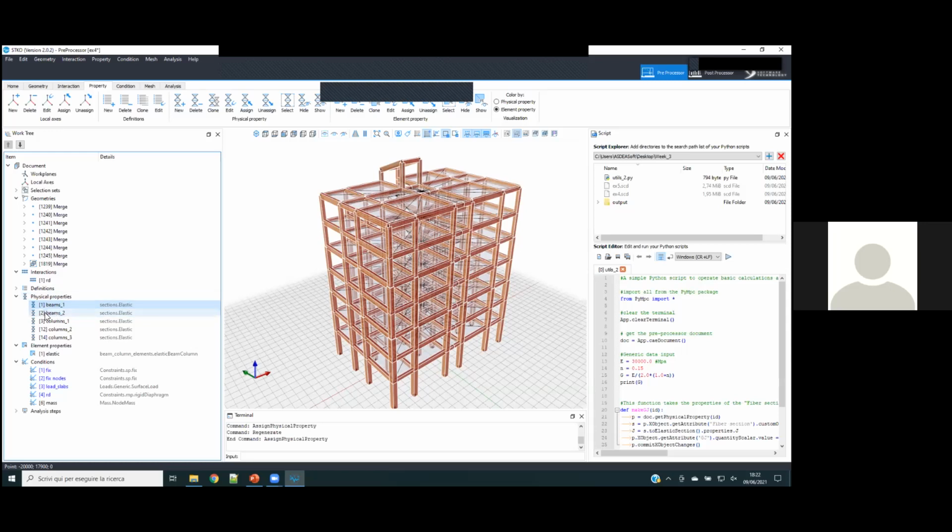And it's created automatically by STKO, but it's not regenerated if you erase elements. So for example, here I created some columns and then apparently I changed my mind a lot of times. And I got elements with indices that go from 3 to 12. This is not because of some error. It's because every time I create a new one, an index was generated, and the old index I erased was not overwritten.